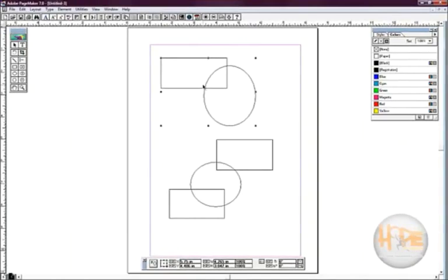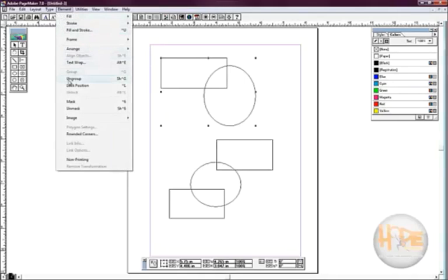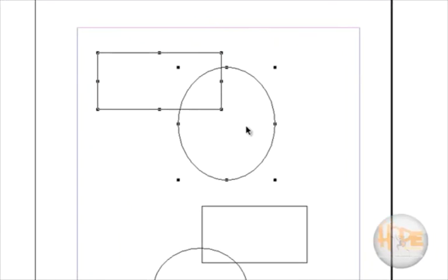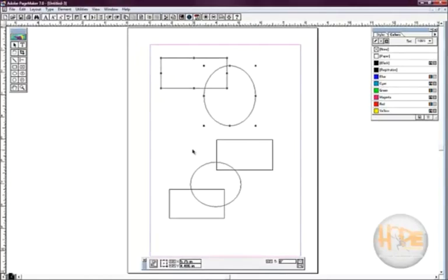To apply the reverse procedure, go into the element menu again, click on ungroup option. See the changes on the drawing area. The two objects again now have different selection handles. Another option that we can perform with the objects is the mask and the unmask operation. For that, we will select the bottom three objects. You have to press the Shift key while you select all the three objects.